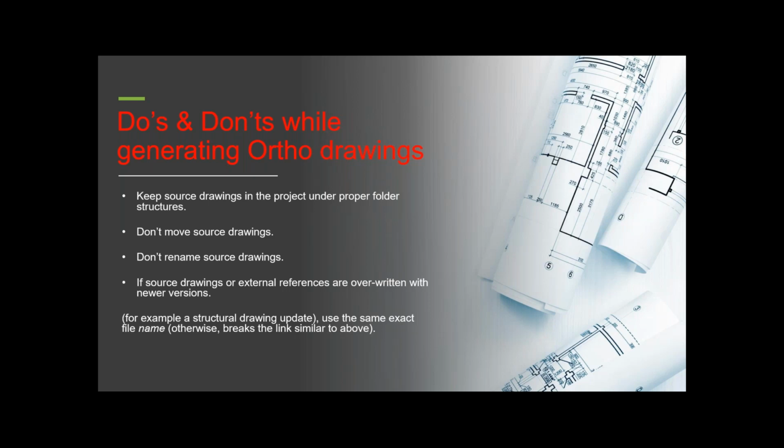Okay, so these are a couple of don'ts with respect to naming and renaming of your drawings, specific to ortho function. The next one is if source drawings or external references are overwritten with newer versions. This can happen, especially when you're migrating your project to a newer release, or if your external drawings were saved on a newer version and brought over. In those situations, try to make sure you create your new orthographic drawings just to create the associativity again.